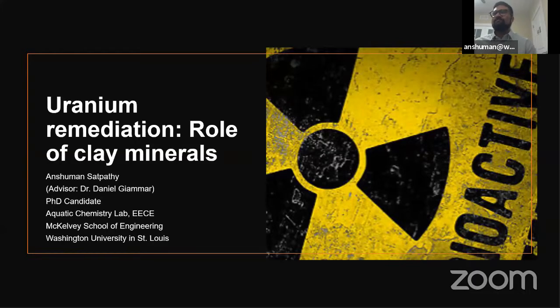Likewise, we have arsenic, we have all other heavy metals, which are of a lot of concern. And the sorption chemistry essentially depends on the pH and the charge, whether it's cationic or anionic, and what pH range we are talking about, and carbonate loading. So these are the factors, and oxidation state, of course, because that determines the charge behavior of the heavy metal.